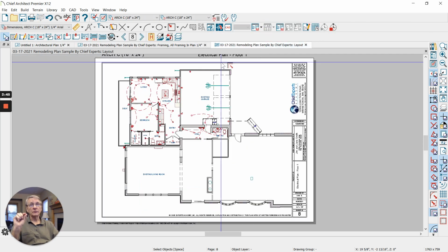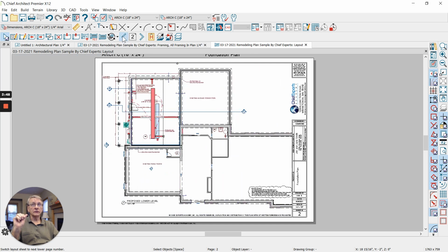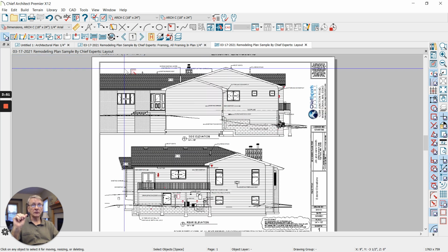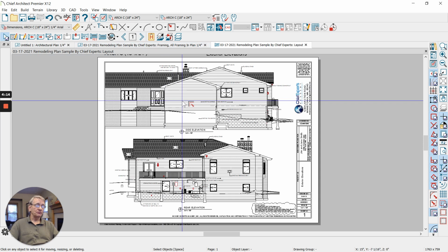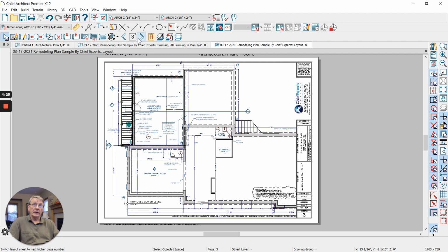So now, when it comes to assembling the working drawings that you're going to use to create your working documents, here I've got my elevation. Again, in the Home Designer Pro version, you get one page. You get a page like this that you can put some things on. When you want to create a second page, you have to create a brand new file, and you have to put all your stuff on that file as well. So you might create the first page, do a save as, delete the view that's on the page, put your new view on it, and you'd be good to go. Make a copy of that, delete it, put your stuff on it, make a copy of that, delete it, put your stuff on it, go adjust all your layers, turn them on and off.